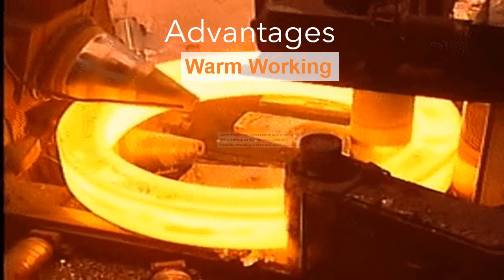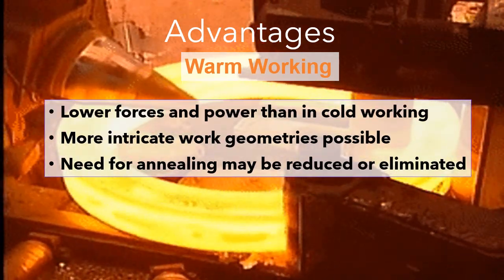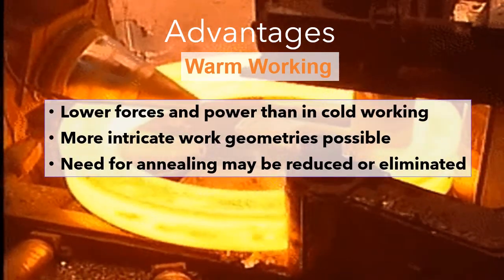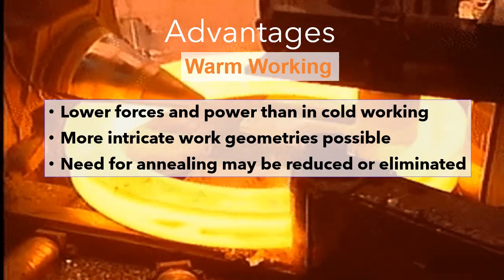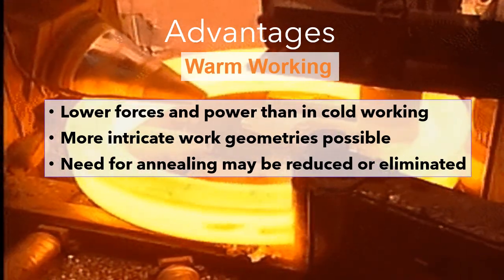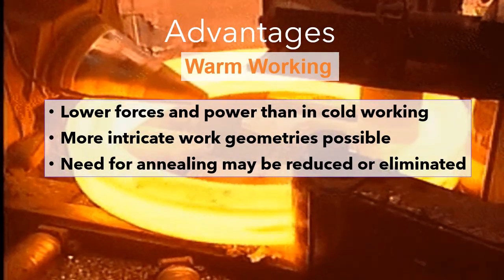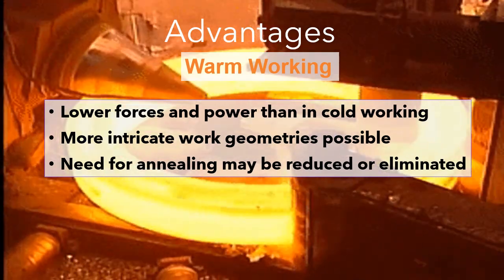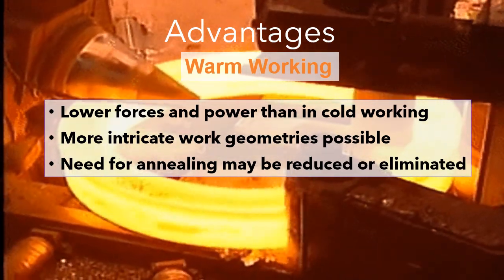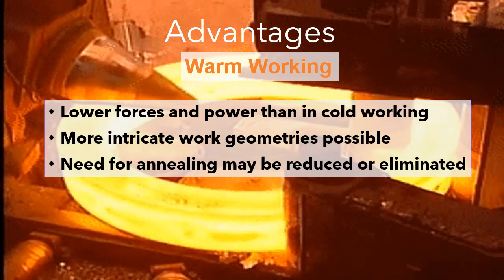In warm working, lower force and power than cold working are required. Also, more intricate work geometries are possible. As the process requires some heating and cooling, the need for annealing may be reduced or eliminated.